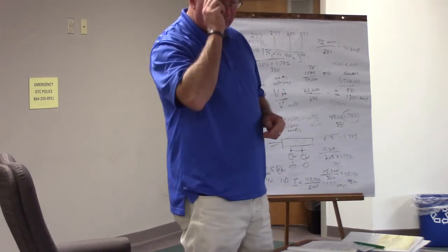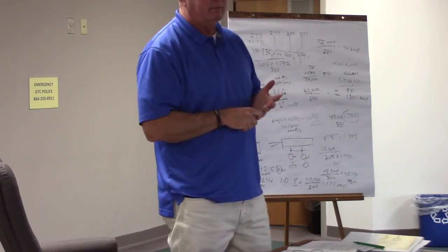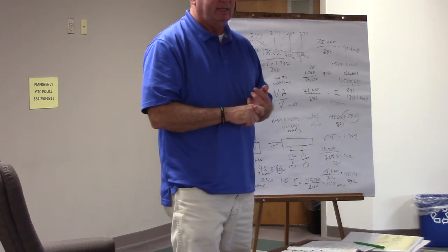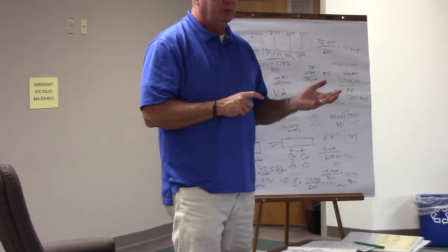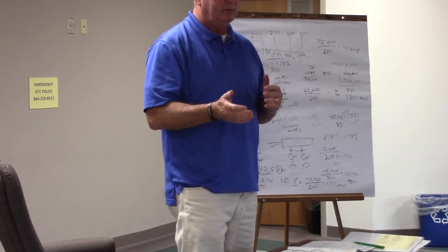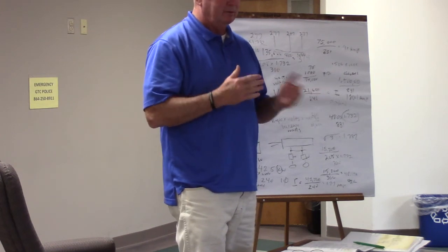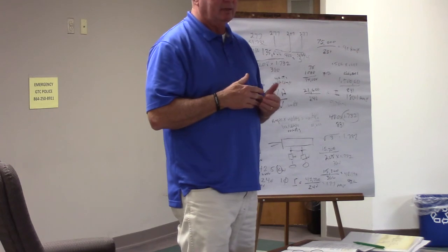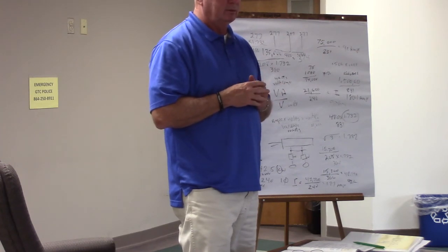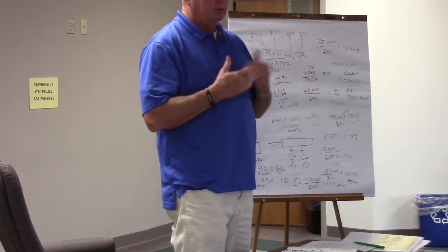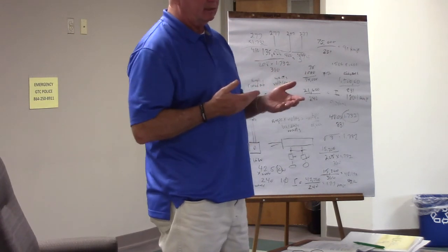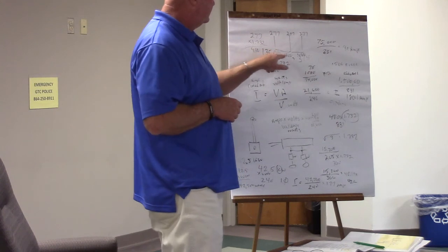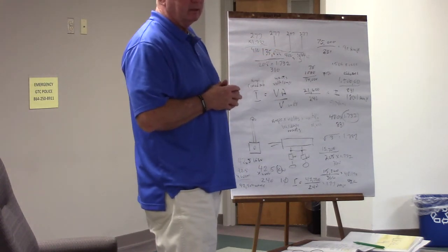The biggest thing is understanding, A, anytime you have kVA, make sure you change it to 1,000, and B, if it's 3-phase, that you're looking at your voltage, 480. The 480 represents your 3-phase voltage, so don't be mistaken in multiplying 277 times 1.732, you'd be wrong. And like 120/208, you're always doing the 208 times 1.732. So the 208 or the 480 represents the voltage in between the legs, not each leg.